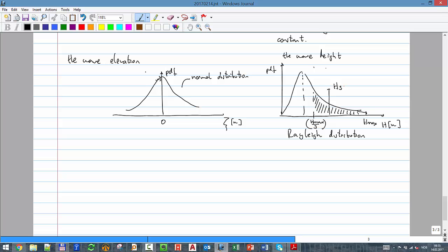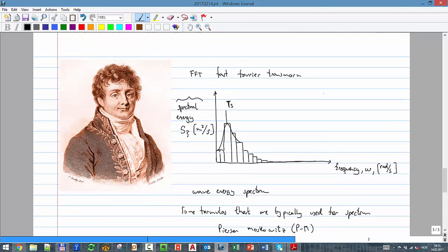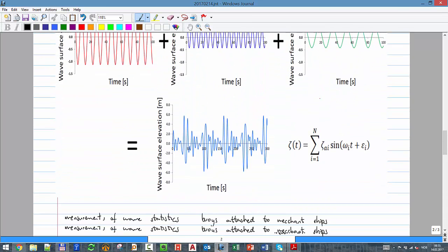We're trying, just not to confuse you, in that period, that very complicated wave, to get two indicators. Remember, we need two things. We need something indicating the frequency, and you see already how we have done it: take the fast Fourier transform and get the peak. Very simple. But we also want some indication of amplitude, of height.